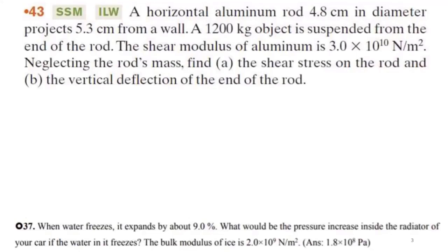So here I have water, which is freezing. And if it's not straightforward, don't be shy to ask a question. When water is freezing, it expands by around, let's say, 9%. Now, the question is, what should be the pressure increase inside the radiator of your car if the water is frozen there?